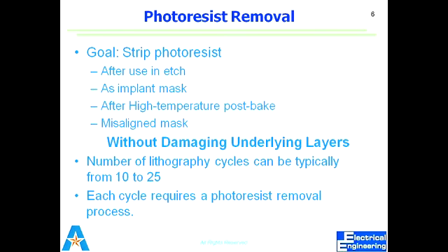That's why, when working with more than one photolithography process on your device, you always keep in mind that the underlying layers are not sensitive to the steps or the etching process that you use for your specific desired layer.